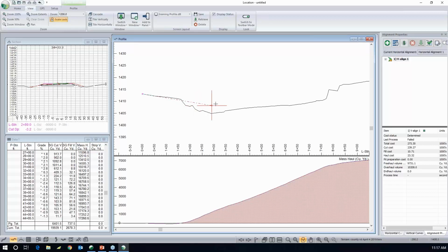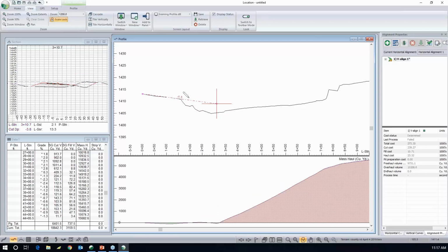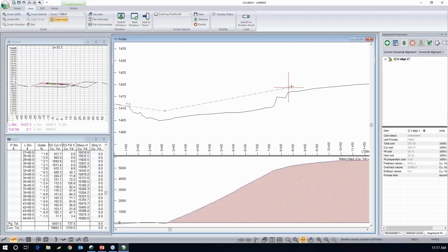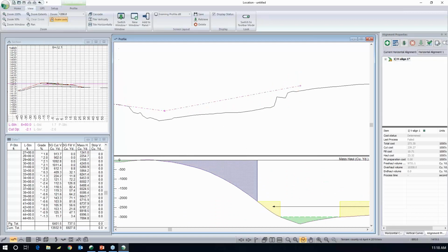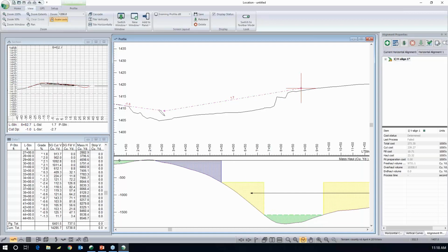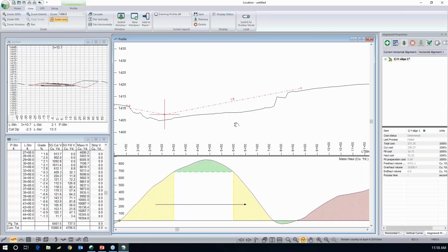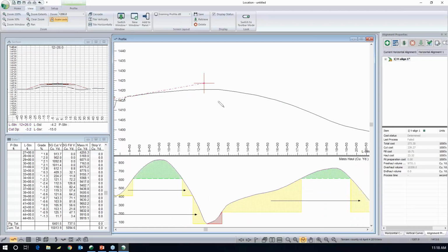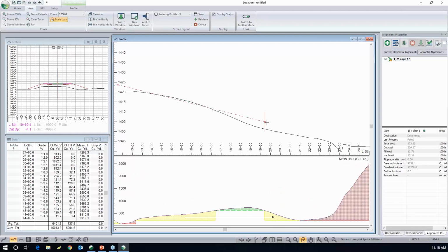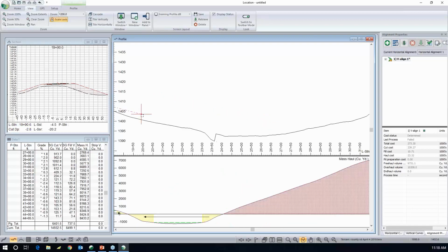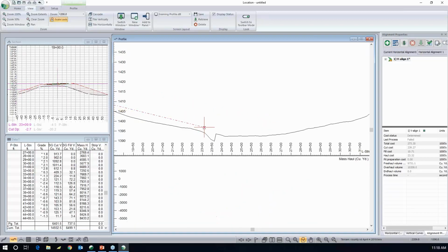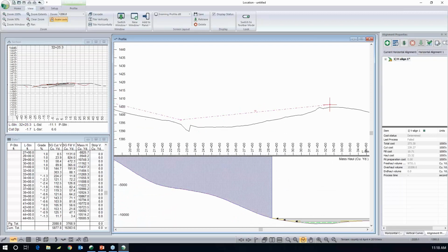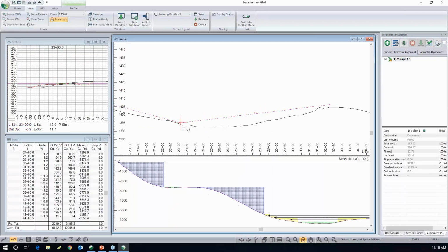All right. Left click once. You get a grade automatically attached to the alignment. Left click. Try to get as much of this waste rid of as I can. Now I got some borrow going on. Pull that down. Move that alignment all the way up here. Come back down to this side of the slope. Got a little bit too much borrow again, so I'm going to pull down to create less borrow, more cut.